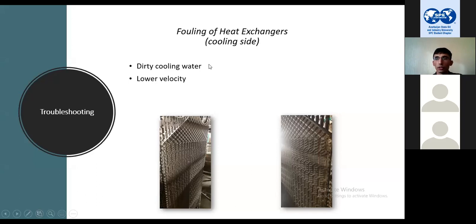Biocide is used to kill bacteria inside the cooling water, and anti-scale is used to chemically remove ions like calcium and magnesium, in order to prevent further scaling of those salts. Corrosion inhibitors are chemical compounds used to decrease corrosion rates of the materials in which cooling water is flowing.